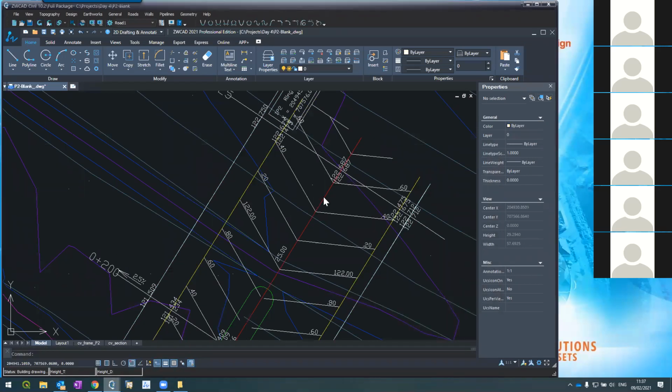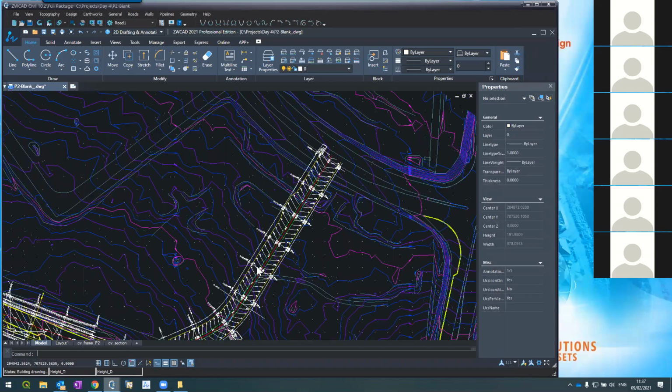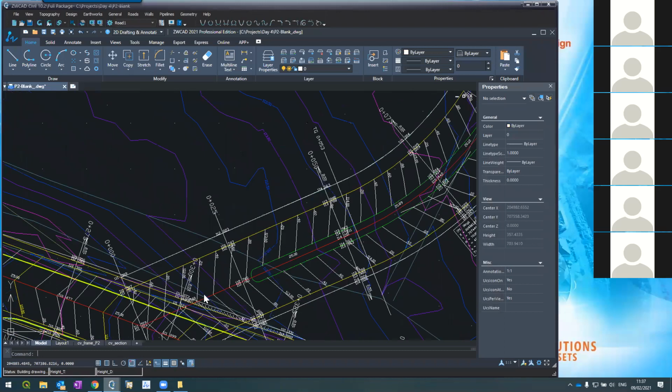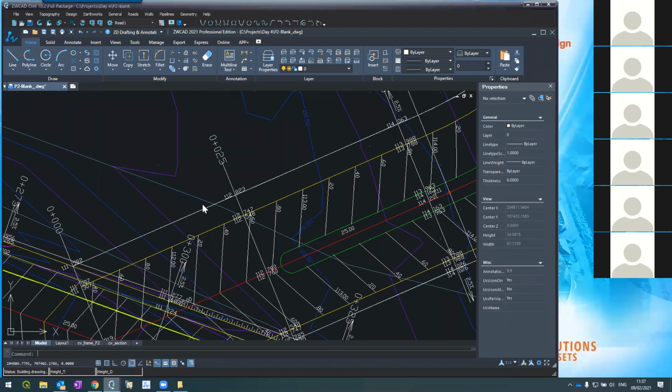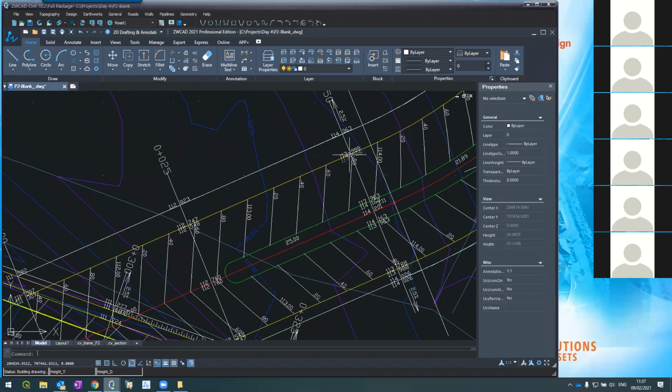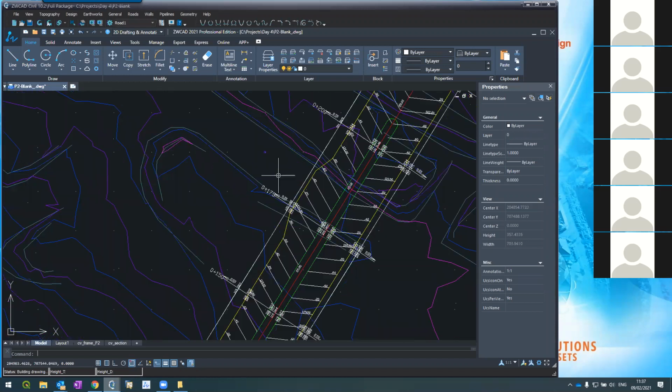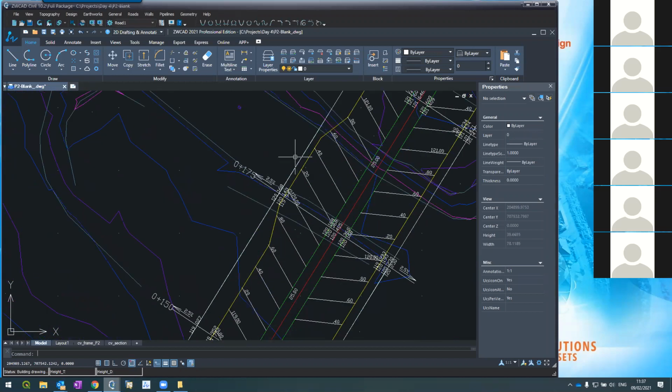Here it is. The system automatically went and created all the elevations, the slopes. Here it's a different template, so it knows not to put contour lines here. Here it knows how to use the same slope, 2.5%, but wider.